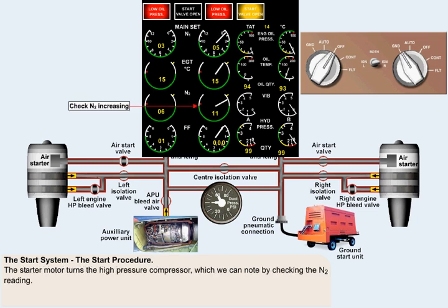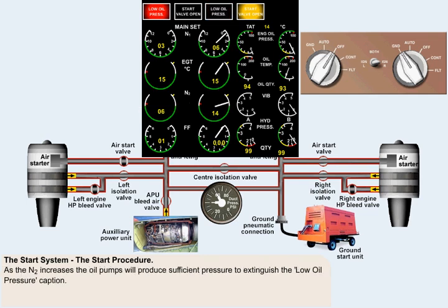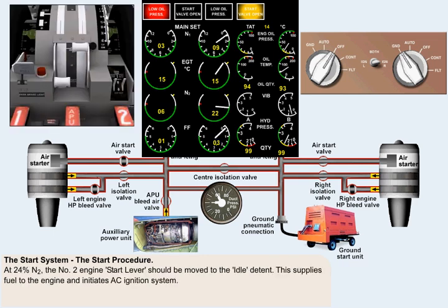The starter motor turns the high-pressure compressor, which we can note by checking the N2 reading. This is an appropriate time to start timing the starter motor duty cycle. As the N2 increases, the oil pumps will produce sufficient pressure to extinguish the low oil pressure caption. At 24% N2, the number 2 engine start lever should be moved to the idle detent.